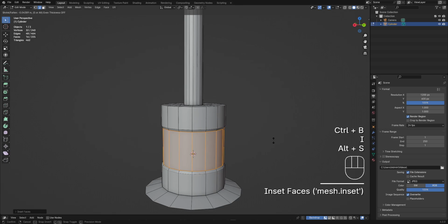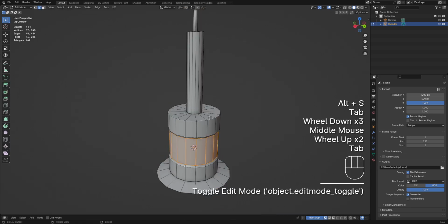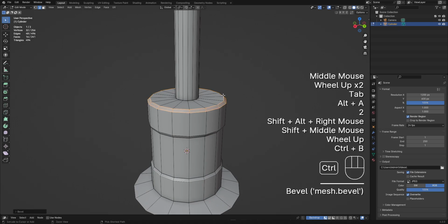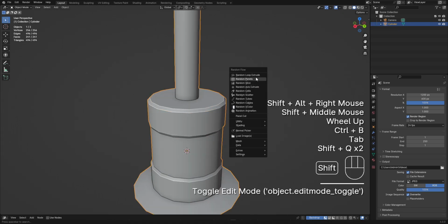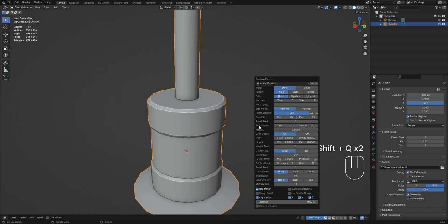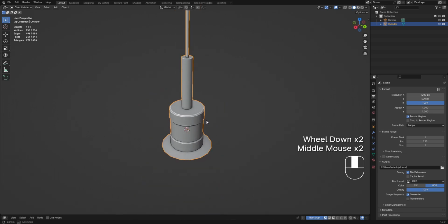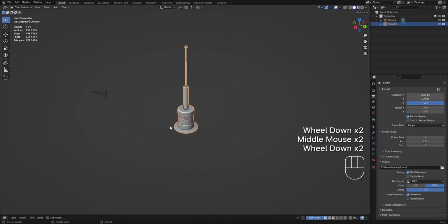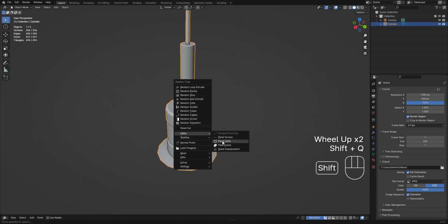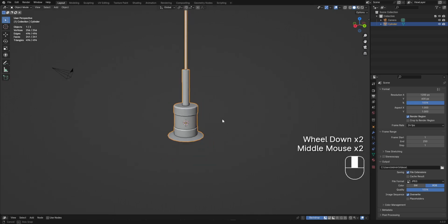Also, I'm going to show you what you can do to create the details without having to use the subdivision, or in this case, the cut parameters or the subdivision parameters. We're not going to increase the subdivision. Instead, we're going to use the actual geometry of the base mesh and create details, merge detail using the plate inset. So we can use random panels, but for this video, we're going to use plate inset instead.